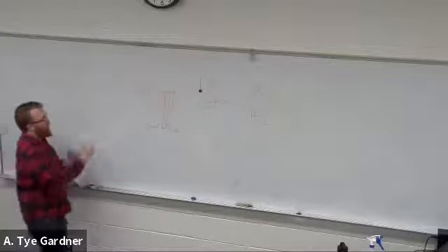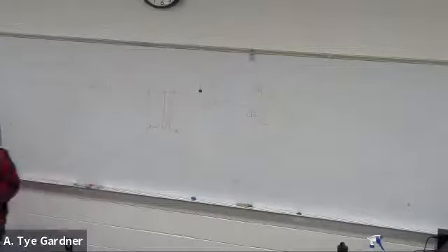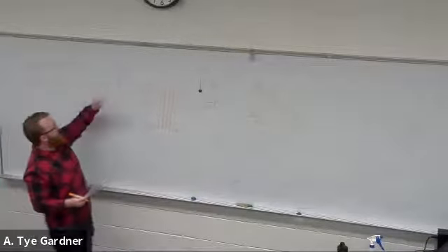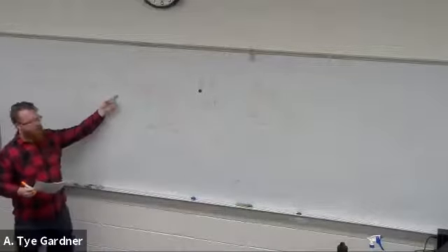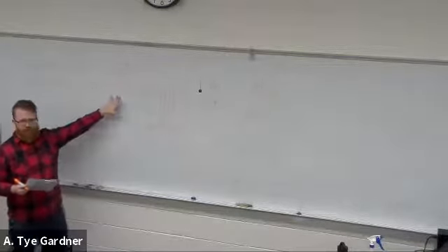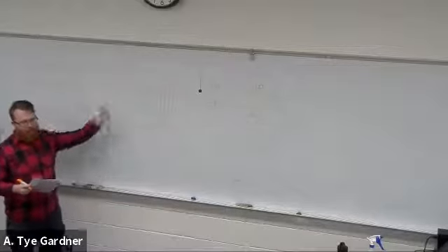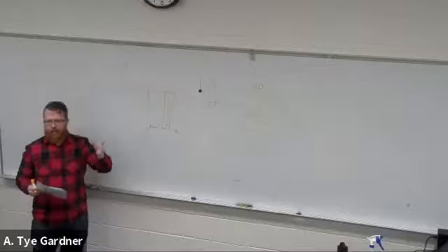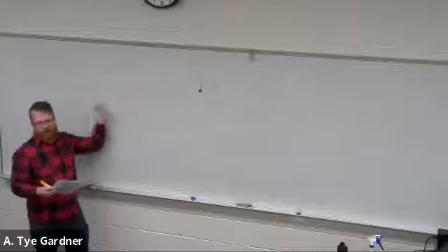Alpha is what we call the TCR, which is really just your temperature coefficient of resistance. And I will always make fun of mechanical engineers for this, my younger brother is a mechanical engineer. I always like to call them table engineers because they like to go and look things up in tables. So if my metal is copper, I need to go look up what is alpha for copper, right? To determine how this change in temperature is going to affect my resistance.